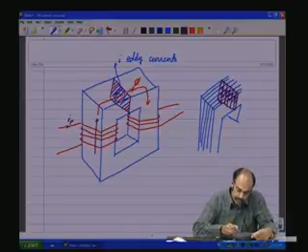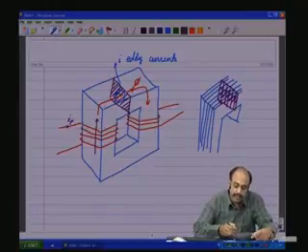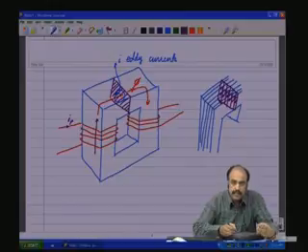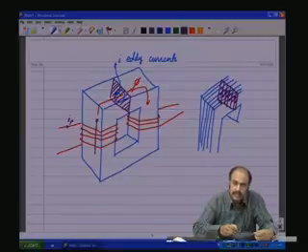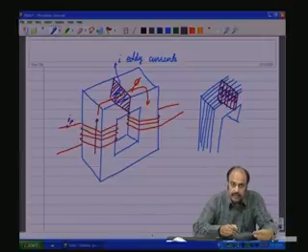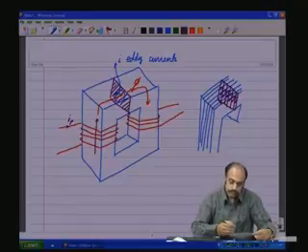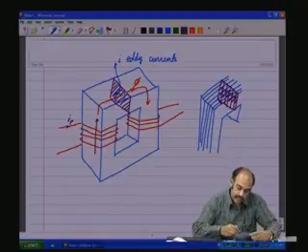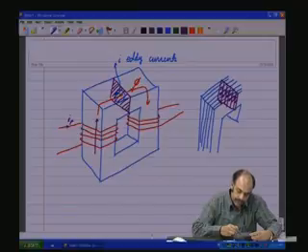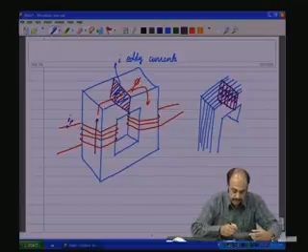So, what basically happens is, for the direction of the current flow here, the rho L by A is increased. Rho L by A is the resistance, with rho the resistivity of the material. The resistance increases because the cross sectional area for the flow of current here is reduced, and the length is also reduced, but still the resistance is increased. So, once the resistance increases, the resistance for this cross sectional area for this lamination here will be much higher than for the solid mass, which has a much higher cross section area.